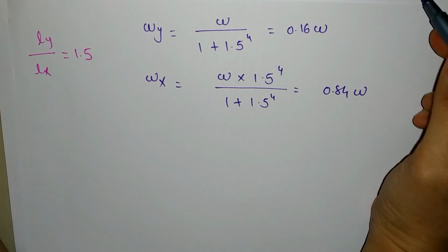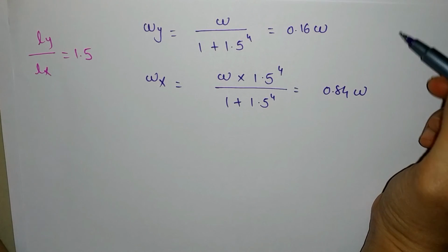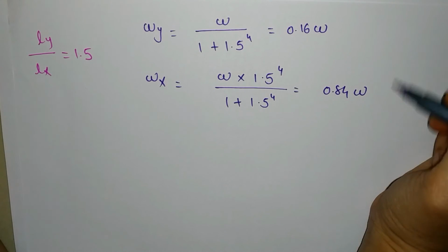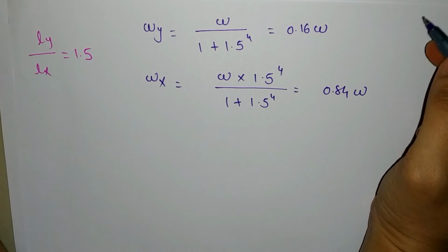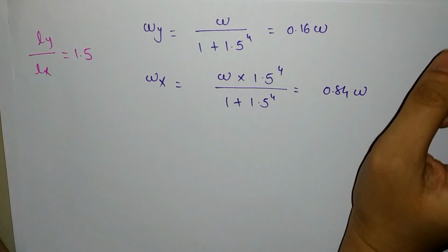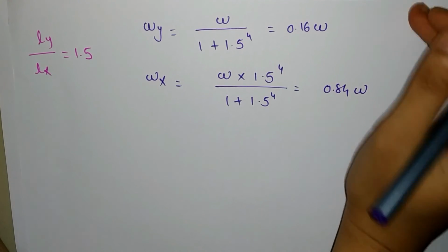We cannot say equal load distribution, but both directions carry some amount of load, so we have to provide main reinforcement in both directions.